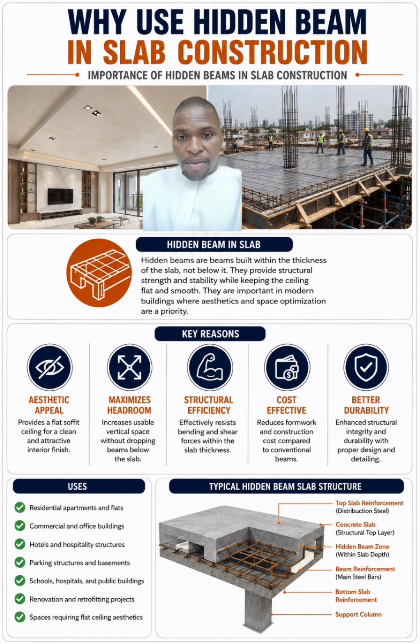So here is a typical hidden beam slab structure. From this picture you can see how the hidden beam looks. This is a slab structure, and you can see the reinforcement for the hidden beam inside, within the slab structure. The top slab reinforcement is what we have here, which is the distribution steel.